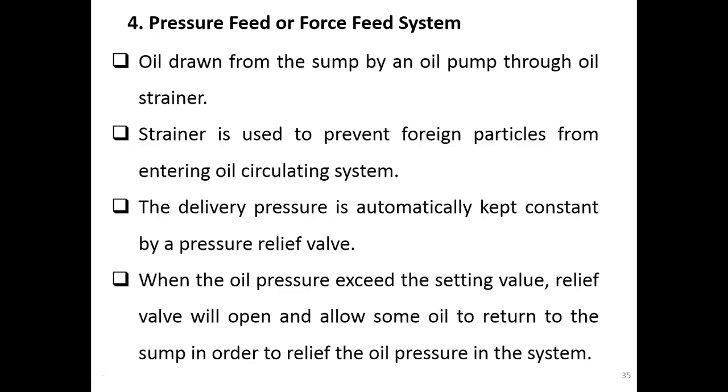And we also have a pressure relief valve that is installed in this system. This pressure relief valve is to maintain a constant oil delivery pressure. So the oil pressure will not go beyond the pressure that's set, and the delivery pressure is always constant.